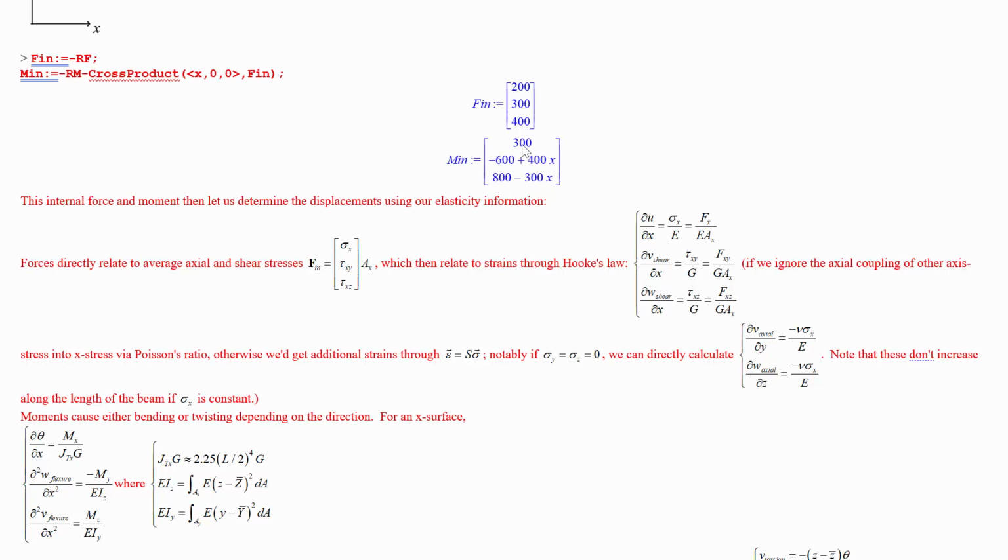Next, we have the moments. So the x component of the moment is causing a torsion, right? That's the axial directed moment for this beam that's extended in x from its support, and that is leading to a twisting around the x-axis via the torsion stuff we've been doing this week. But the other two components are bending moments.